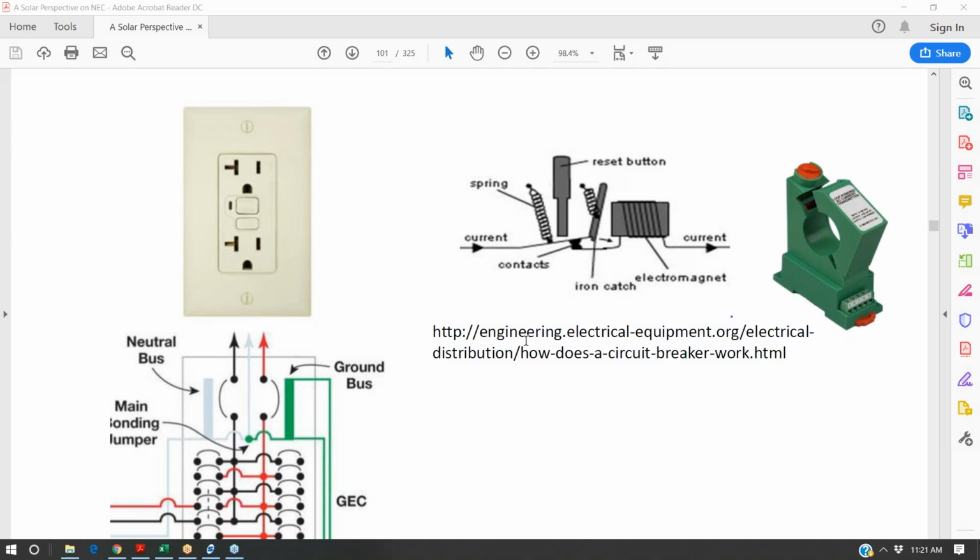So they're more expensive, and they'll trigger not just when you're at your maximum ampacity, but if you have a little bit of current contacting, let's say you pulled a cable through your conduit and you weren't doing things in a workmanlike manner and you scraped the cable jacket. So now there's some exposed conductor touching the side of your conduit, causing a ground fault.